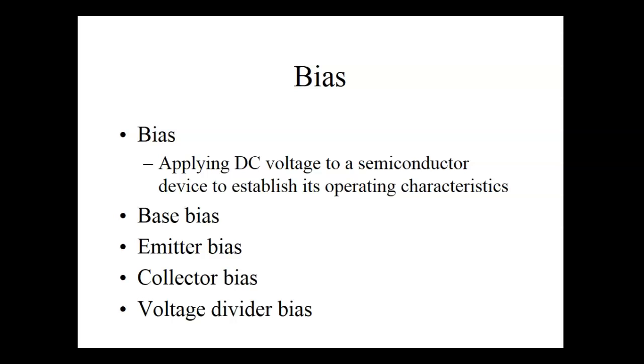FETs have a lot of advantages: they consume less current and less power to operate. They can switch fast because they don't have the stored charge concept that bipolar transistors have. The bipolar transistors are the ones that can handle the power.